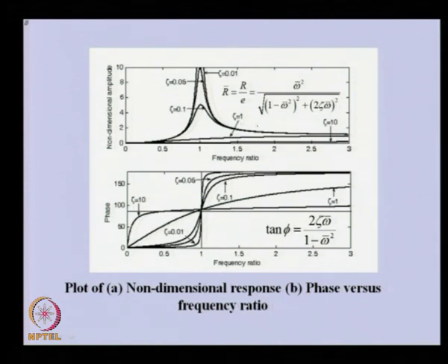And you can see that as we are increasing the frequency, these amplitudes are going toward the value 1, because for that particular case, this particular amplitude becomes equal to the eccentricity, and the rotor tries to rotate about its center of gravity instead of its center of rotation.